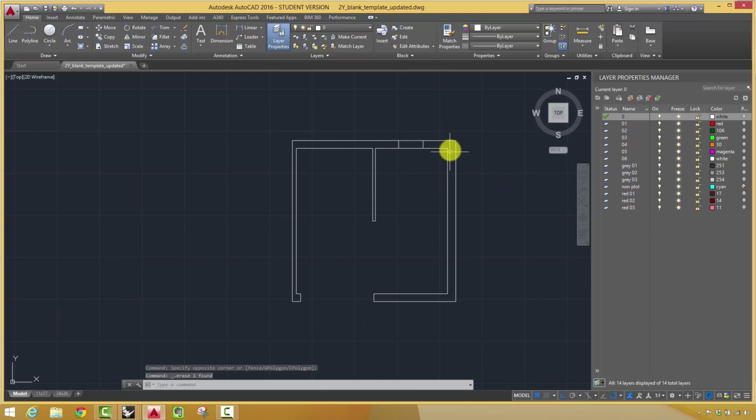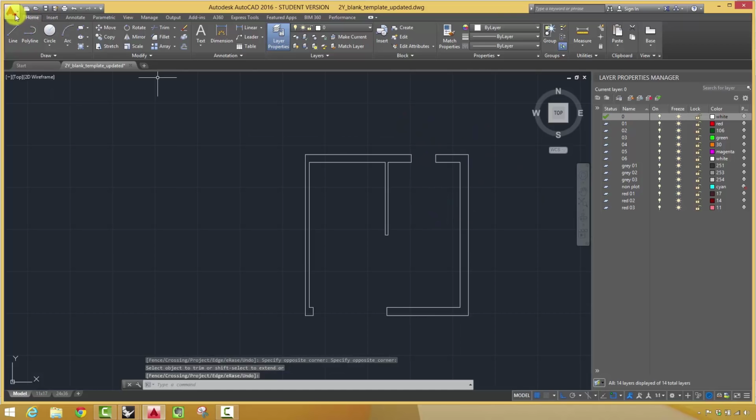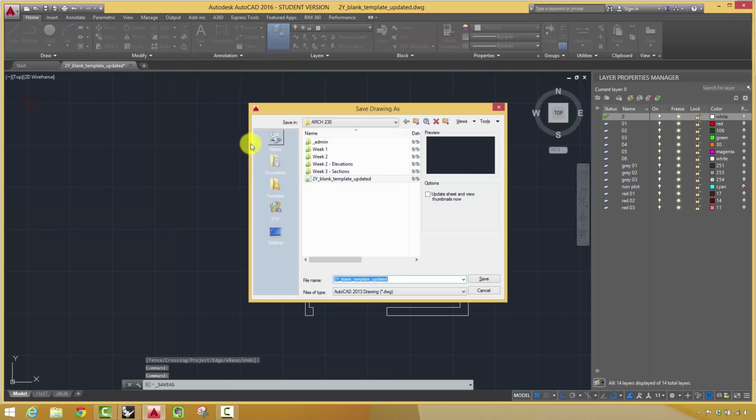And so again, I've let this 1 foot piece kind of win hierarchically, just like this side wins, and then I'm actually picking up this wall starting on the inside of the wall, and then on the inside of the partition. Let's finish this up by trimming. And that's not too bad. At this point, I would probably save my file, just because I've been doing a lot of work lately. So let's just call this my section plane.